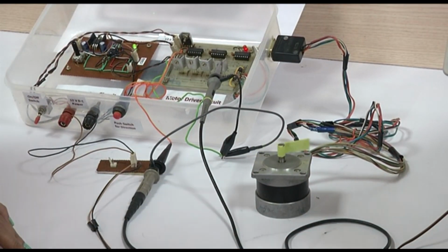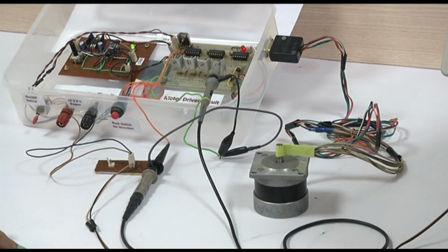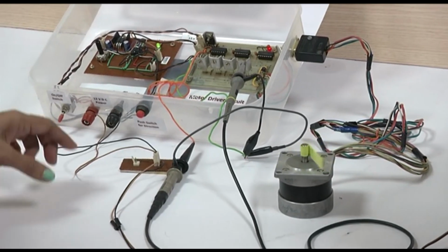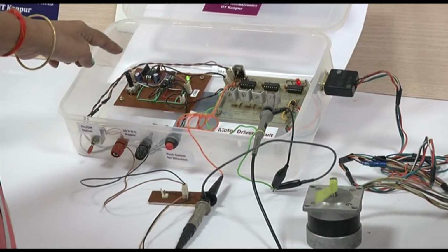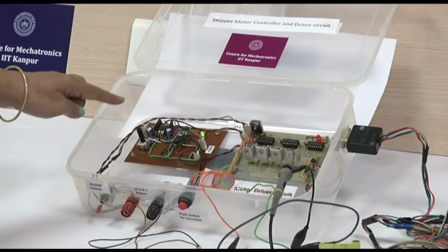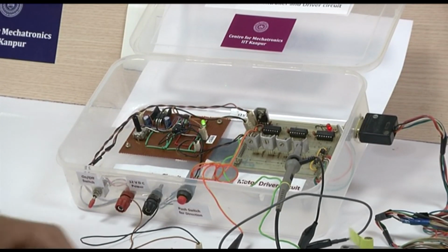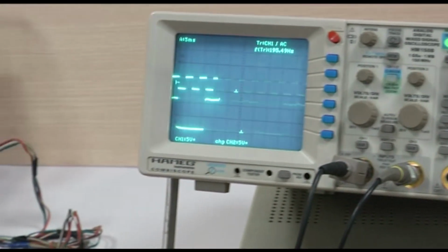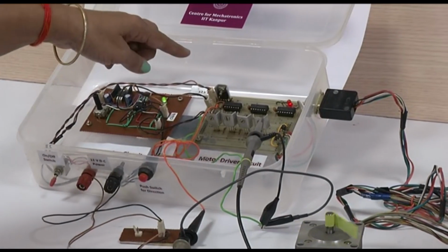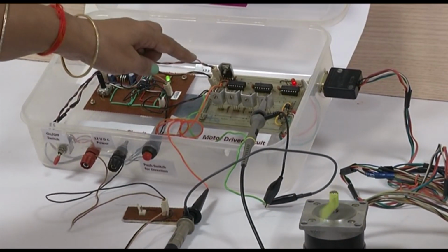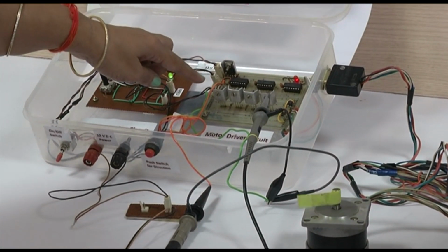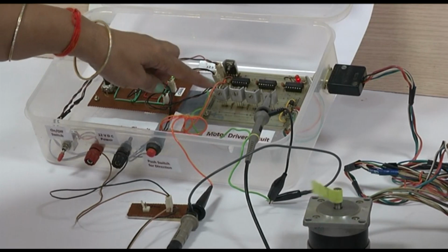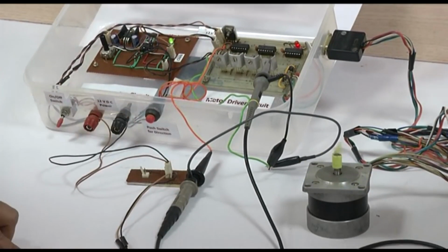So, let us begin with the first module of control and drive, wherein we are using minimum basic hardware to control a stepper motor. As stated earlier, we are using a clock source, a 555 based astable multivibrator, which generates a clock frequency that can be seen here on the oscilloscope. Then we feed those clock pulses to a sequencer circuit comprising flip flops and OR gates, and MOSFETs as the drivers, each MOSFET for one phase. So, we have 4 MOSFETs for the 4 phases of the stepper motor.